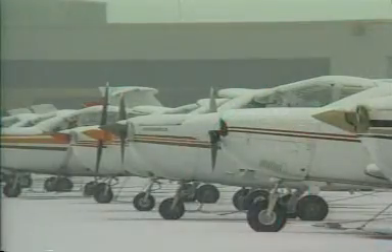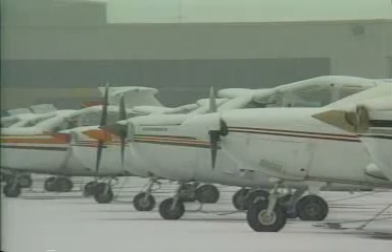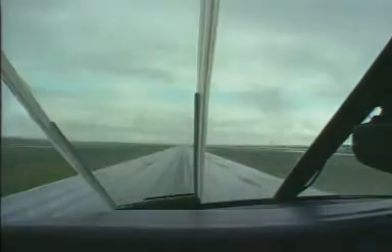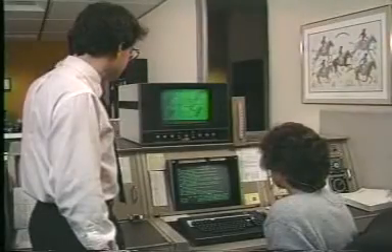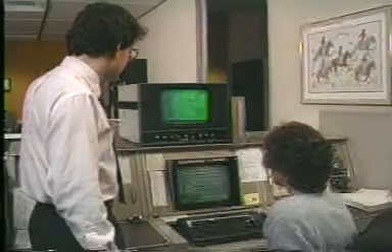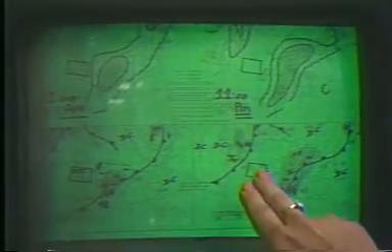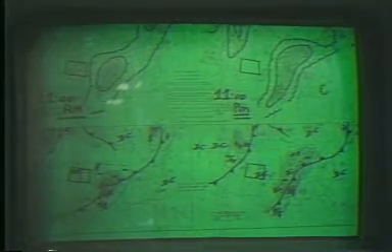Shading is also used to denote the amount of precipitation projected in a specified region. Areas with more than half coverage are shaded, and half or less coverage unshaded. The charts that have been presented in this program are but a few of the graphic weather products that are available for your use. As we have seen, charts of these types are very useful for obtaining a brief, general overlook of the existing and forecast weather along your intended route of flight and the surrounding areas.